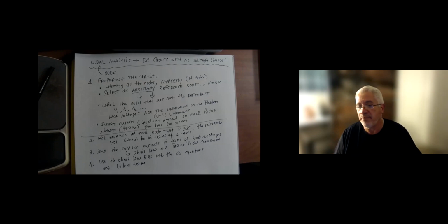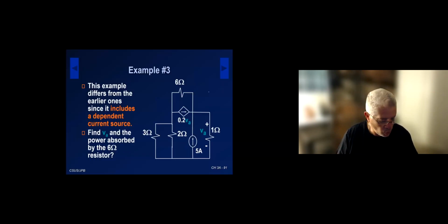Okay, so before I start showing you the solution steps on the PowerPoint, let's doodle on this here. One of the first things when students start taking this course, some students struggle with identifying the nodes correctly. They find more nodes or fewer nodes than there actually are. So what I tell you is, start at any point that's connected to an element. Okay, we start like this, and then we keep going on wires. As long as we're on a wire, it is the same node.